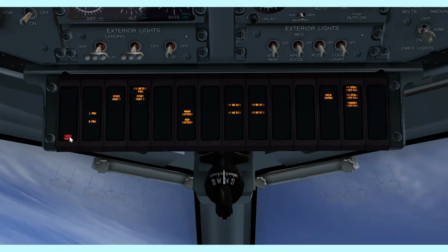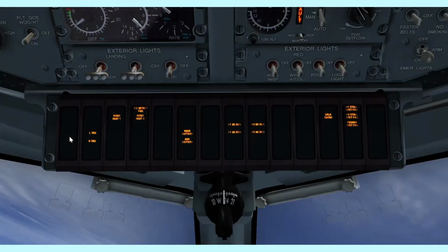So I really hope you understand that this is a very, very serious situation. We don't hope for it at all, but if it does happen, control the aircraft first, fly the aircraft. Immediately the left hand seat pilot puts the MFD1 to PFD, so that the PFD information can be transferred to the MFD, and with reference to that you can fly the aircraft all the way down to 14,000, because you'll depressurize. Then you do your depressurization maneuvers and procedures, and land immediately at the nearest suitable airport. That's all I can say as far as I'm concerned.